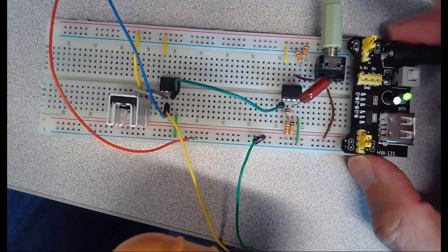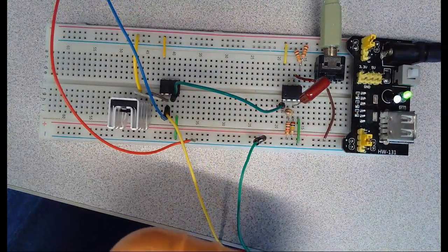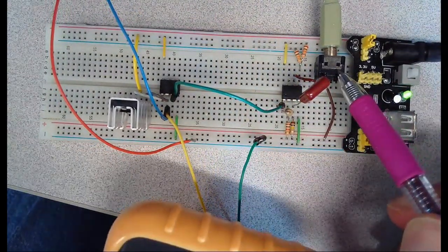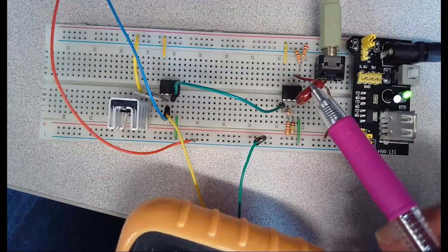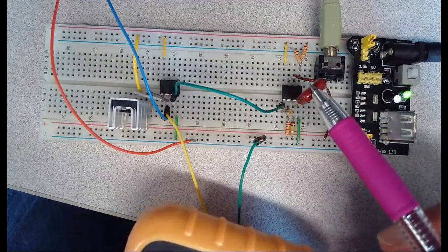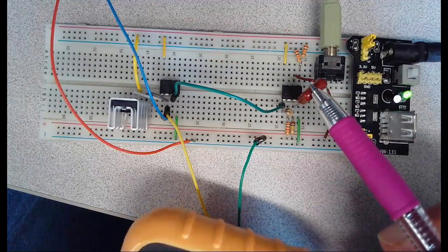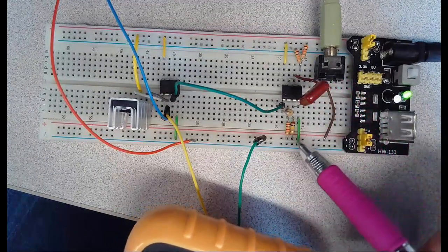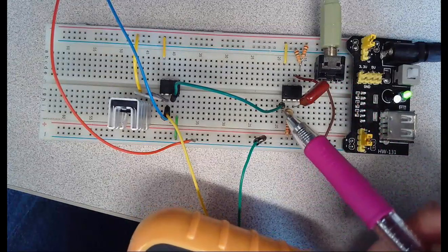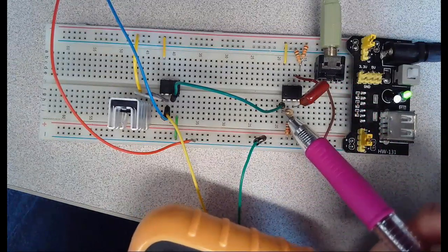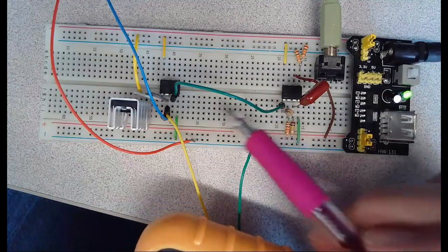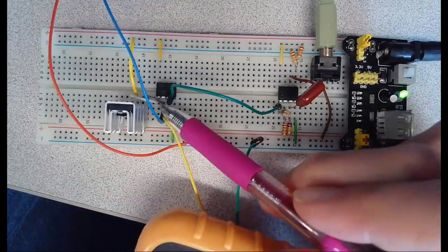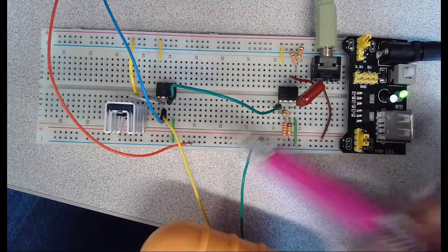Okay, here's the push amplifier. Right here, I've got the microphone going through a capacitor to block the DC because I'm using my computer, and ground is earth ground, not floating. 2.5 volt reference that goes to this line. Here's my times 10 amplifier. I use times 10 just because it was too quiet. Amplify a little bit. It's actually times 11. Goes to the push amplifier. There's my power transistor and my speaker.